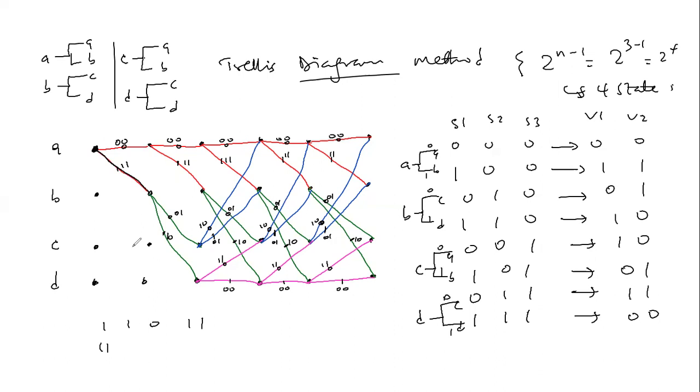So we have 1, 1 from the decoder. Then 1 is emitted again, so it means we are still tracing down. That's 1, 0. Then 0 is emitted, so it means we are tracing up this way. Then 1, 1 is emitted. Then from there, 1, so we are going this way. So that's 0, 1. Then from here, 1 is emitted, so we are coming this way.